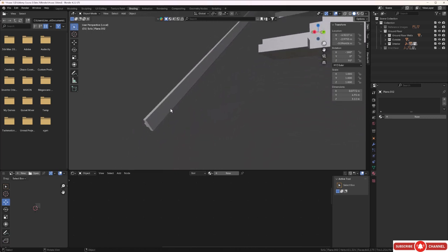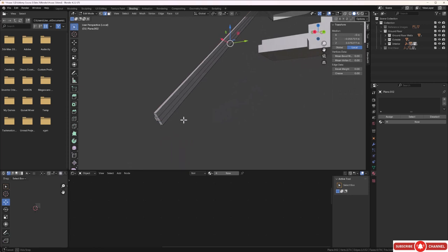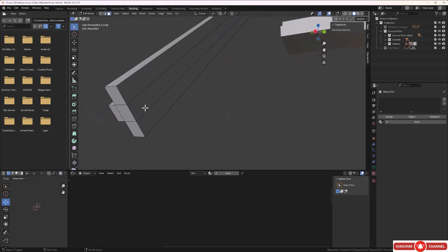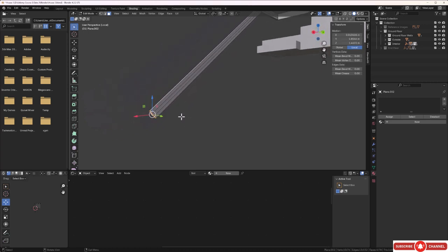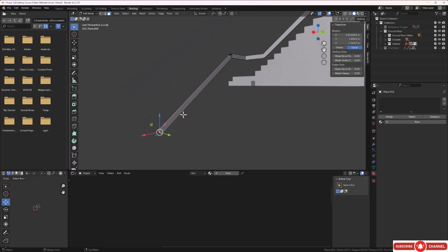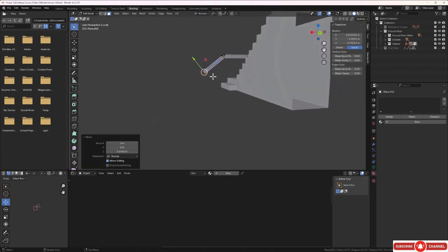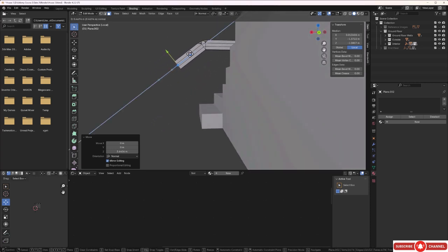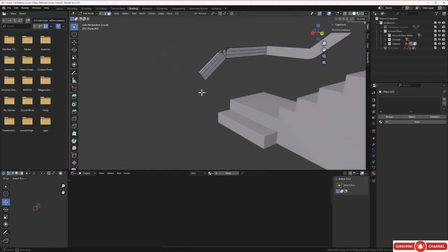So let's actually just collect this one and let's tap into edit mode. And let's make sure we can select faces, so let's press 3. And let's select this face, this one, and this one. And if we tried moving the gizmo right now, it's going to do weird things for us. So let's click up on this again, and let's go back to normals. And let's pull this up here in the Z axis like this. And just see where we want to end this. And I think I want to go to, I would say, about there like that. I think that looks good.